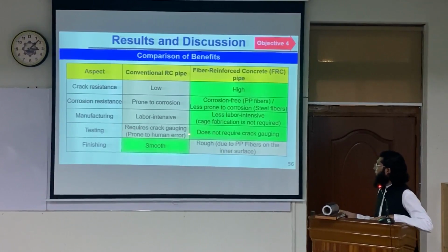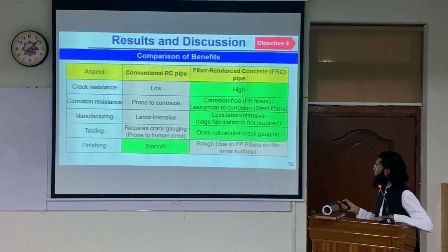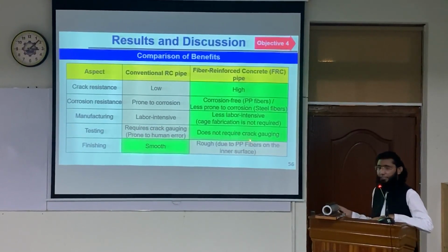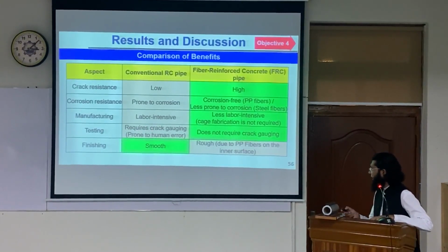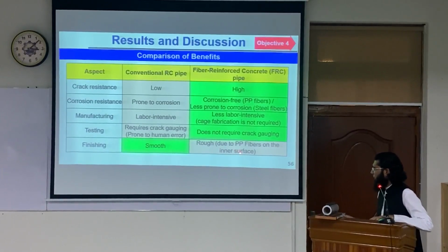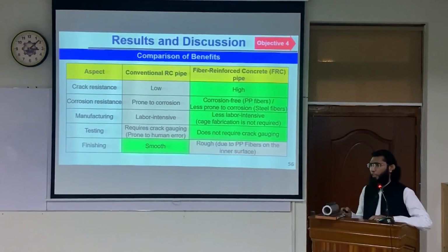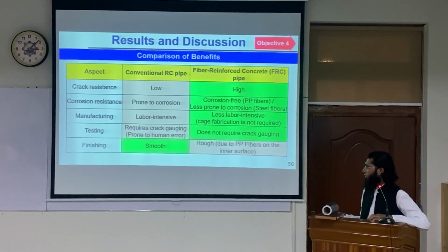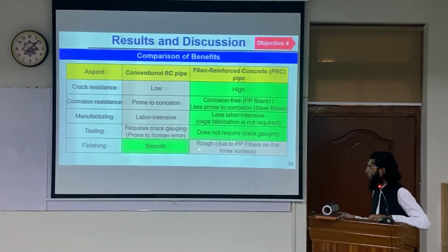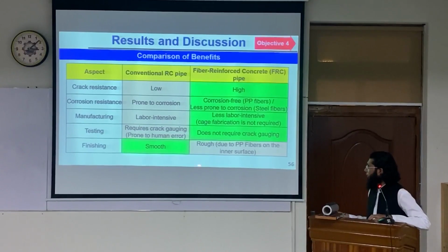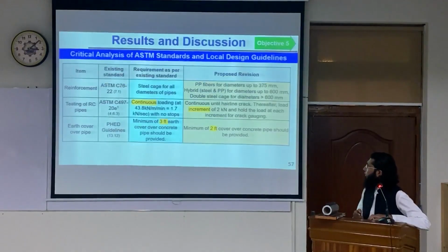Testing has a subjective criterion which could be eliminated if the transition is made to the FRC pipes, because as I discussed, it doesn't require gauging the crack. And one challenge that we faced with the PP fibers coming towards the inner side was that it was rough on the inner side, and this means some more measures would be required, such as coating, in order to achieve better finishing.